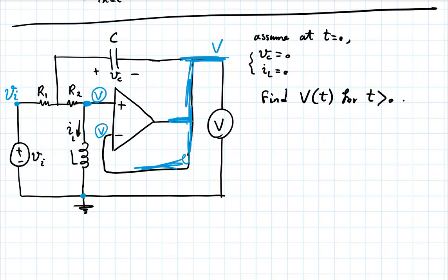But at first glance, giving it the benefit of the doubt, all it's suggesting is that I have V all the way here, and the op-amp will simply virtually connect the two inputs. Again, they're not hardwired, but they will mirror each other. So if I have V on the inverting input, I'll also have V on the non-inverting input. And so far, everything is happy. There's no voltage difference between the two inputs, and the output is a finite value. At the input, I have 0 voltage difference, multiplied by infinity, the op-amp open loop gain, will give me a finite value V at the output.